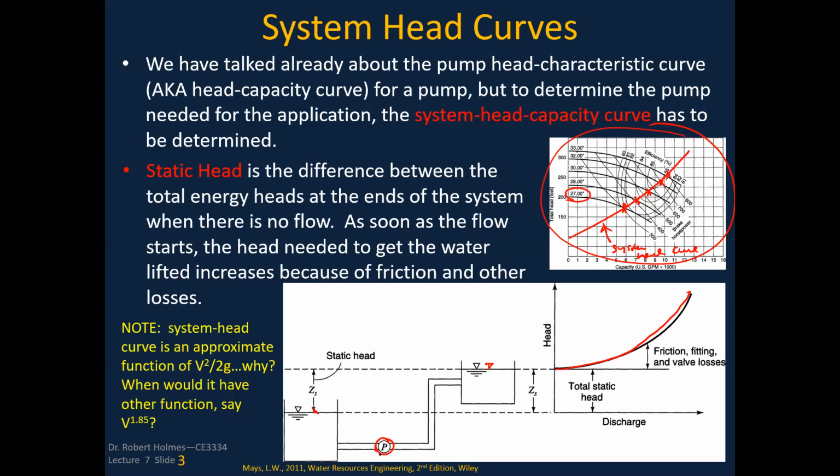If the pump is not operating at all, there's no flow in there, there's a certain static head that it has to overcome. And so there's absolutely no flow that's going to be initiated until I turn this pump on, and then we can assume that as the discharge increases, the pump head has to increase because of why? Because of friction and the other minor losses.